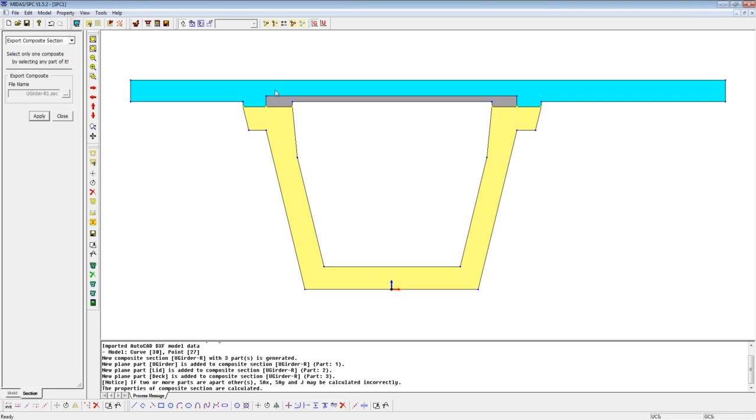So the best thing that you can really do is make different DXF section drawings with different types of haunch heights that you are working with, and you can just throw that into the section property calculator. In one sheet you can fit in as many sections as you want, compute all the properties, and then throw it back into the software for running the analysis and doing a scenario analysis, I would say. I hope that answers your question, David.